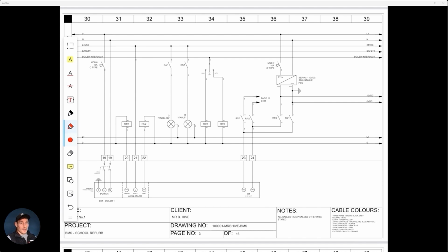But then let's contrast that to a similar scenario, but in the summer, and maybe some rooms are already at temperature in the morning and sufficient and comfortable for the kids and the teachers, but maybe there's some rooms that are sort of out of direct sunlight, maybe in the shade, that are a bit colder, and it's just a few of those rooms. Then we might have the boilers fire up maybe at 30 degree, 40 degree, 50 degree heat, because that's going to be enough to achieve that temperature in whatever time frame's been decided. So that just gives you a quick idea of what I mean by demand.